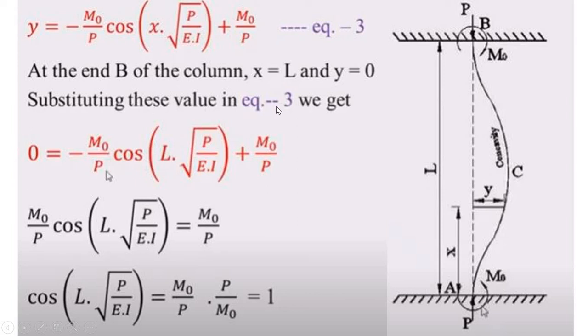Substituting these values in equation number 3, we get 0 equal to minus m0 by P cos of L into under root P by EI plus m0 by P. And solving that equation, you will get cos of L into under root P by EI equal to m0 by P into P by m0, which is equal to 1.